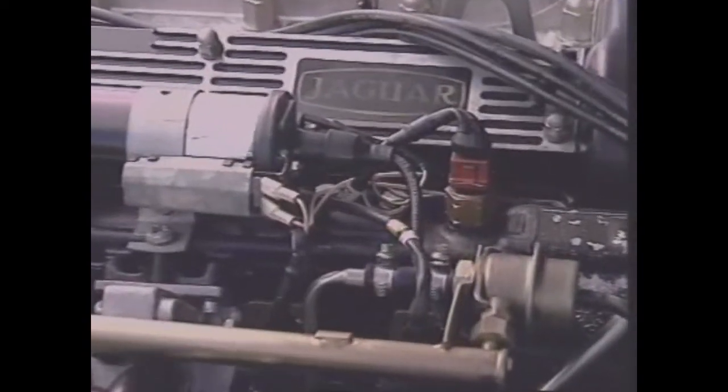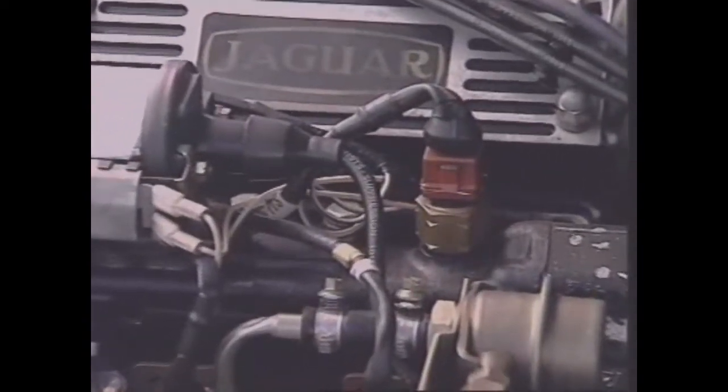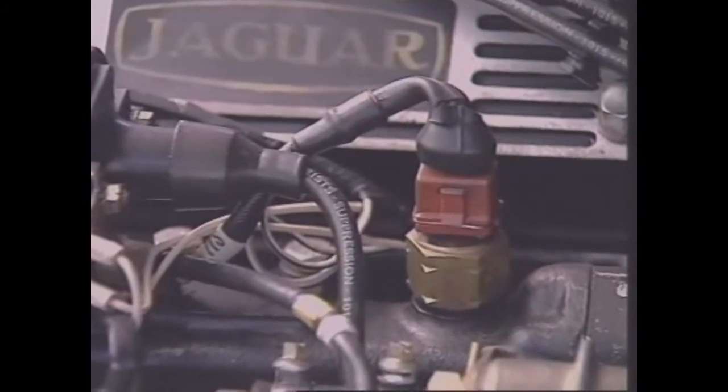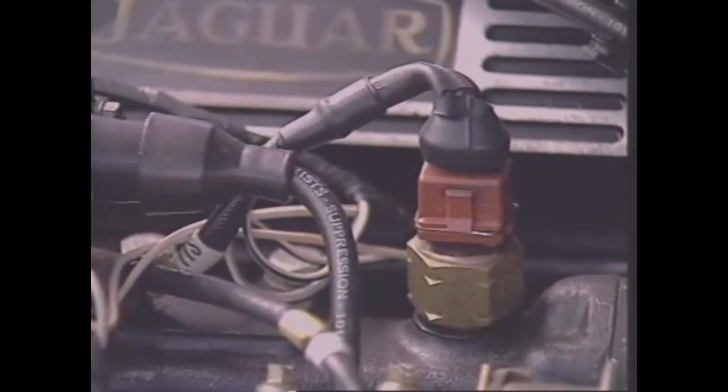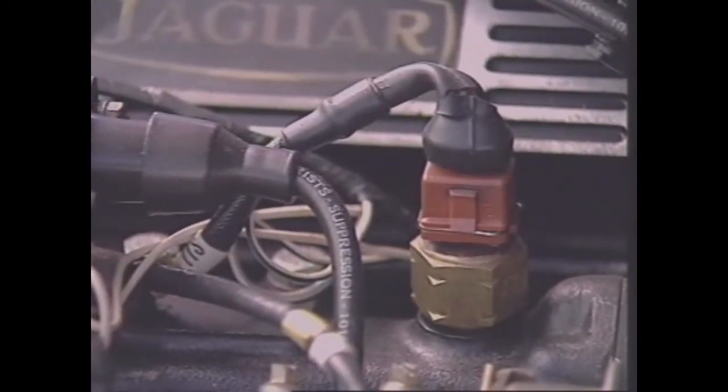It's supplied with fuel under pressure from the fuel rail and only operates when the engine is cranking. A switch called a thermotime switch immersed in engine coolant completes the electrical circuit. It controls the operation according to engine temperature. This ensures the injector operates under cranking conditions only when the engine is actually cold.